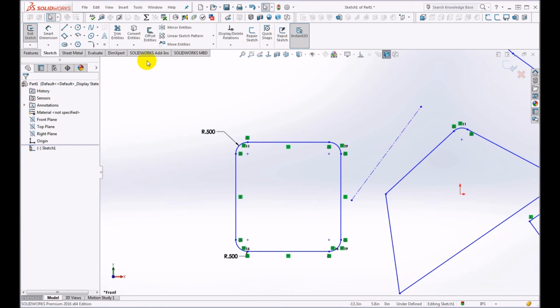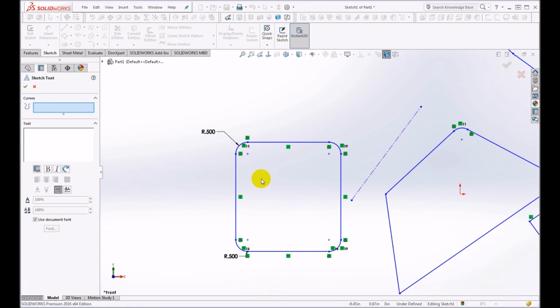Okay, one more here and then we'll finish up this video. There's a text tool. If you have the need to add text on the actual part, and you'll see there are instances where you may want to emboss or engrave text into a face, frequently used for like 3D printing or things where you have that opportunity. I could, for example, say hello world. Those of you in programming will like that. Got to spell it right here. Hello world.